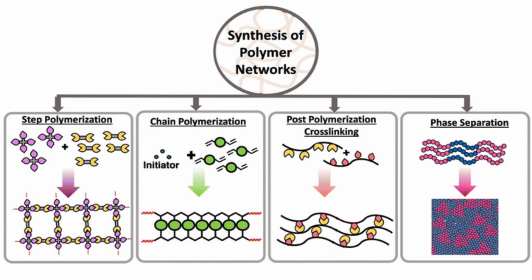Additionally, several statistical theories have been developed to correlate the network topology and viscoelastic properties. While these models effectively determine average macroscopic properties in many cases, they often assume an ideal network formation and largely overlook the network defects, including various loop orders and free or dangling chains. These defects deteriorate mechanical performance and affect the material's durability by lowering the overall elasticity of the network. Characterizing the microstructure of polymer networks through experimental techniques is challenging, particularly in capturing topological features.